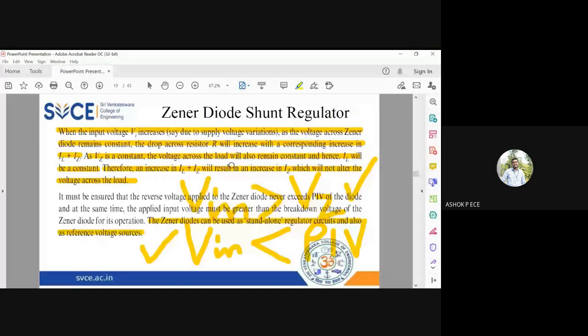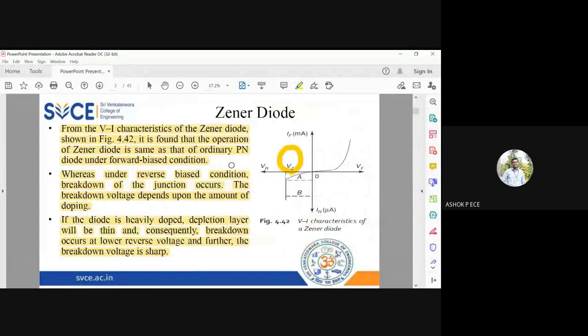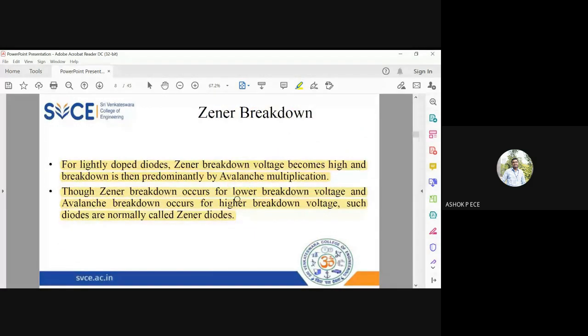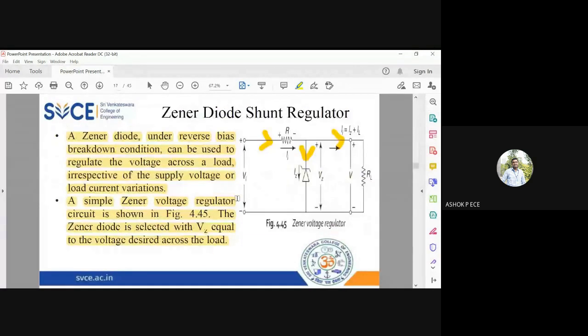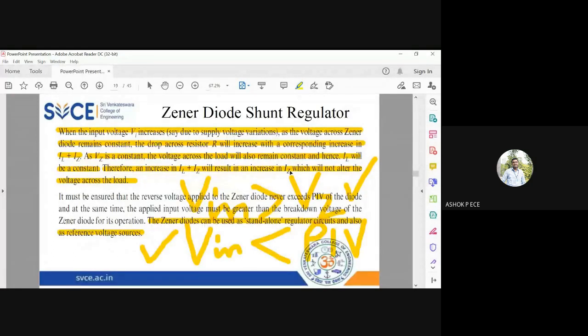Okay, so that is what I have on the Zener diode. In exams, mostly they might ask the construction and operation of the Zener diode, but sometimes they will specifically ask you to explain the voltage regulation property of the Zener diode. In that case, you have to explain what voltage regulation is, what line regulation and load regulation are, and then you have to explain this circuit, and say how any change in input voltage is going to be automatically adjusted by the circuit, which provides a constant output voltage.